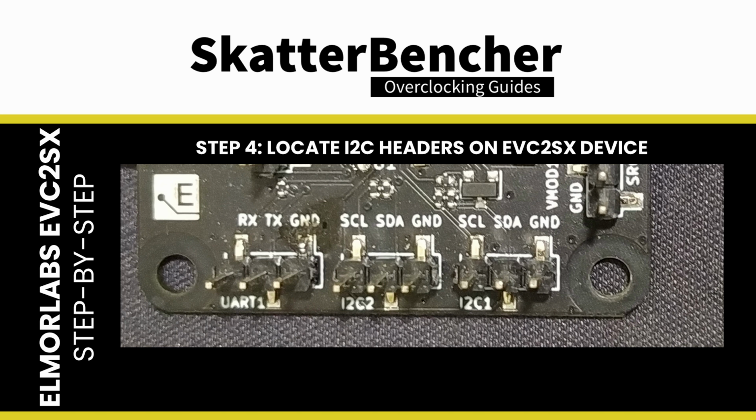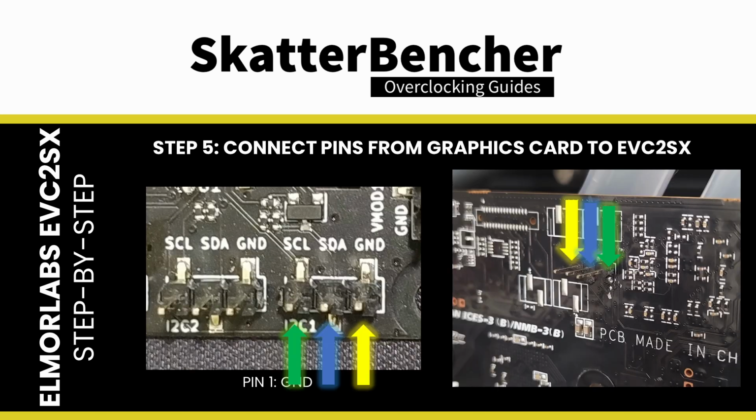On the EVC2SX, each I2C header has 3 pins: SCL, SDA, and GND. That stands for serial clock, serial data, and ground. It's essential to connect the pins on the EVC2 to the correct pins on the graphics card. Connect the various pins to the relevant points on your graphics card. Since there are only 3 pins, it should be straightforward. If you're unsure, use a digital multimeter to locate the ground pin on both the graphics card and the EVC2 I2C header. The data pin is always in the middle, and the other pin is the clock.